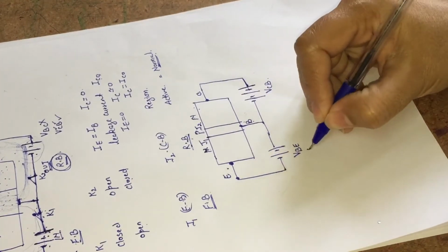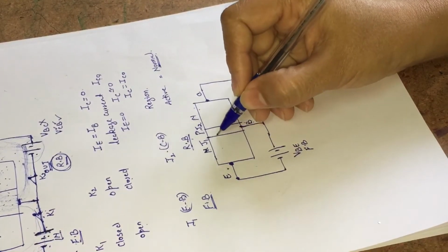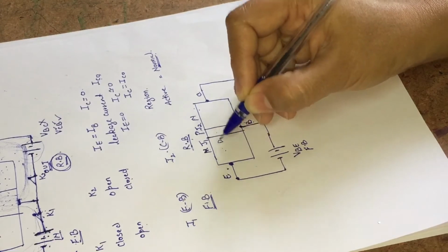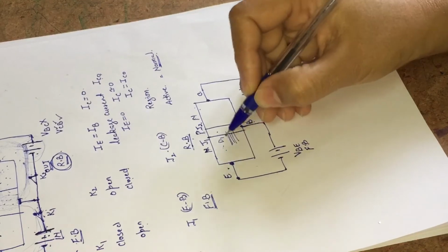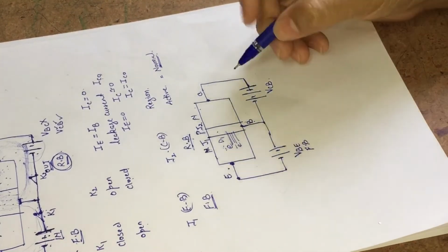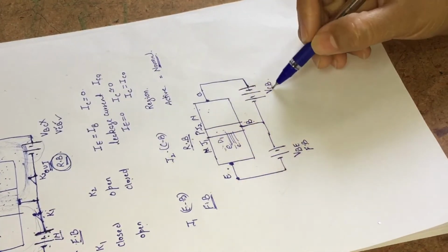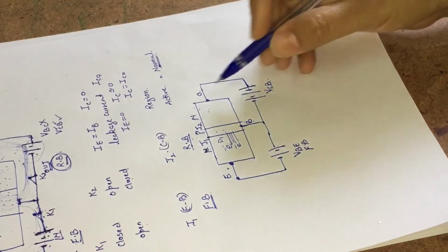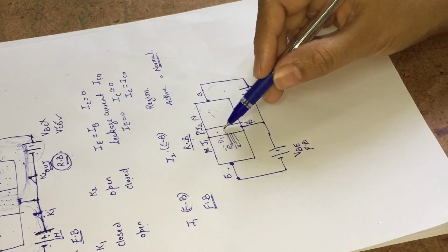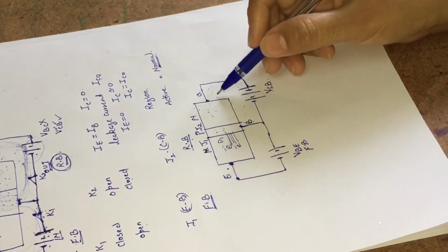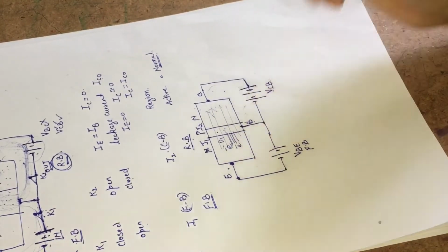In this case, as the first diode, the emitter base diode, is forward biased, there is a flow of current, a flow of electrons. And where the collector base junction is reverse biased, there will be no current of its own on this side of base and collector. The collector current totally depends upon the emitter current.